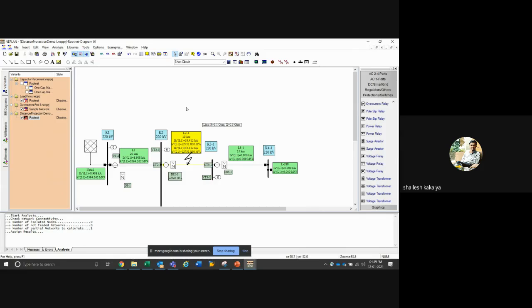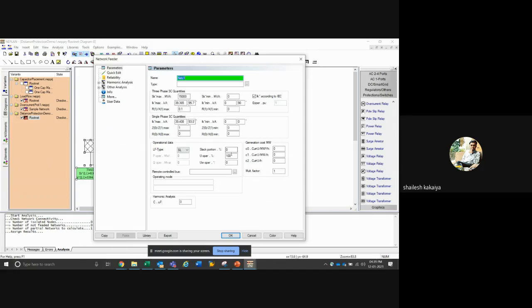Phasor measurement units and phasor data concentrators are input devices. There's no direct interface like a SCADA or EMS for this. But we can take the inputs from those and feed them in to say that this was the kind of phase angle existing at this bus, and this is the kind of short circuit level existing at the equivalencing bus. I hope I was able to answer your question, ma'am.